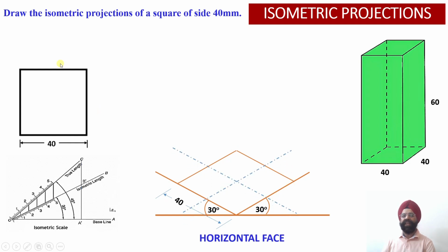Now let us read out the statement. We have worked out the center point of this edge, and the center point of this edge. So the axis line can be drawn over here. This is my center line. Similarly, work out the bisector or midpoint of this edge, and of this edge. So once again, the center line has been completed on the base. So this will give me the axis of the square prism, right?